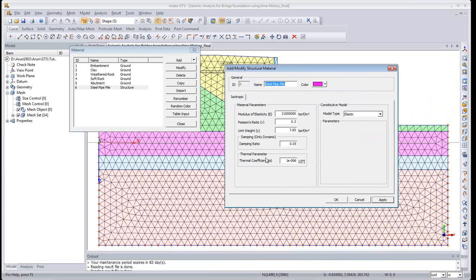And for structural members, as you know, in geotechnical problems we assume them to be within the elastic range and they are not yielded. So we usually assume elastic type of material behavior for structural components such as concrete and steel, unless it is really needed, then we do a non-linear type of analysis.